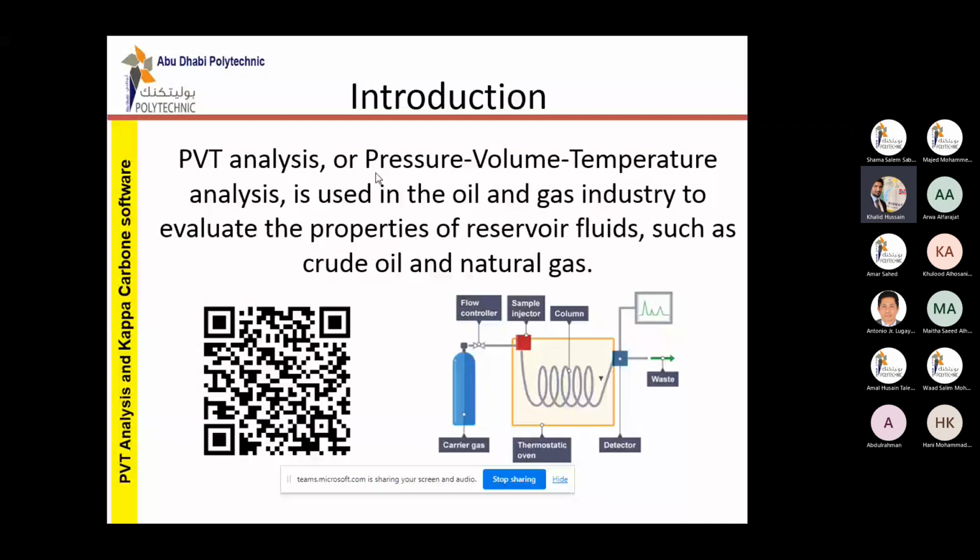The pressure that can force us to change all the facilities on the oil field. Facilities mean a lot of separators, processing units, pipelines. There's a pressure value that can force us to change the whole infrastructure. At that pressure, the reservoir produces its first bubble of gas. What is it called? Bubble point pressure.